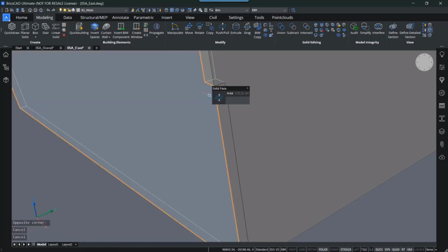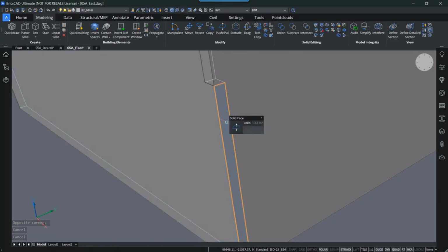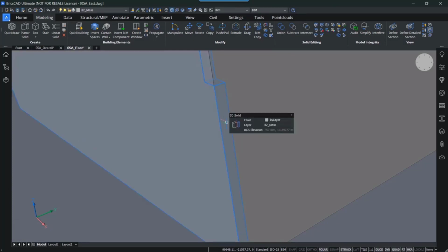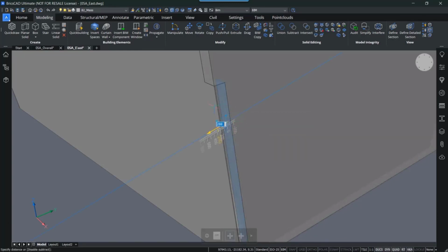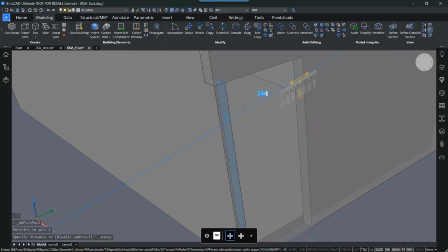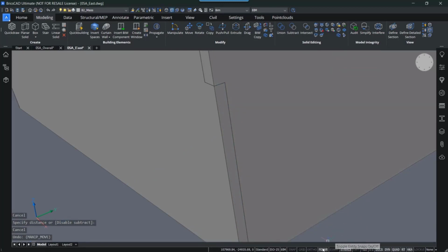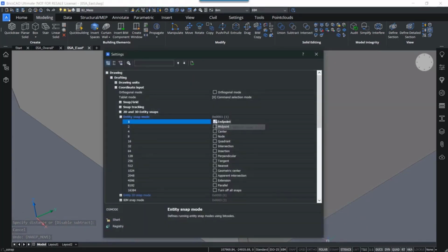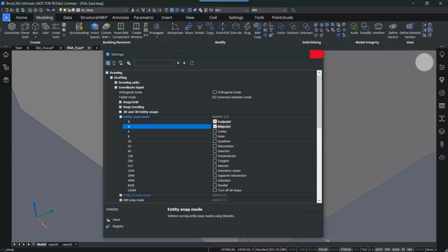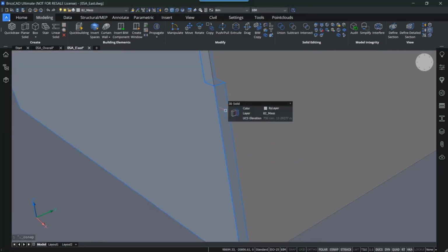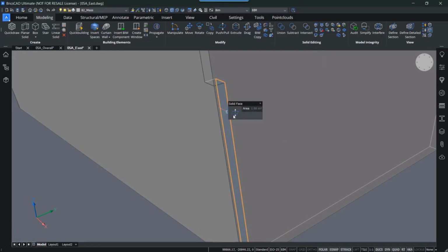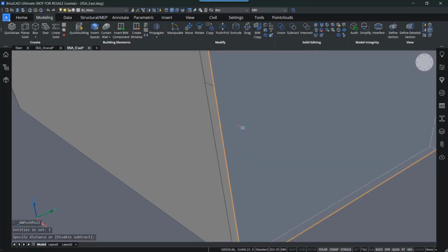So what it does is, if I zoom in and then enable prioritization on selection of faces, I can hover over it somewhere here and press Tab to toggle between the different layers underneath. So I toggle until I have this layer, and this is actually the back face of the other wall, and I can use push-pull to push it forward. And if I have the E-snap on, of course, I can enable E-snap to endpoint. Okay, so again, using Tab, choosing the back face and then pushing it forward like so.